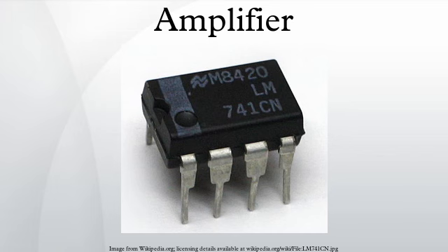Amplifier design is always a compromise of numerous factors, such as cost, power consumption, real-world device imperfections, and a multitude of performance specifications. Below are several different approaches to classification: input and output variables. Electronic amplifiers use one variable presented as either a current or voltage. Either current or voltage can be used as input and either as output, leading to 4 types of amplifiers.